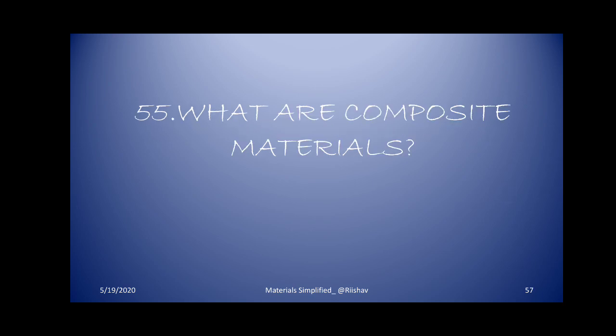Okay, what are composite materials? Well, yeah, composites are a combination of 2 or more materials. Okay, like one of them is matrix, another one is reinforcement. See, generally each of the materials we are using must exist at more than 5%. Okay, there are 2 different phases. One is matrix, which is the continuous phase, and another one is the reinforcing phase, which can be continuous or discontinuous both. So basically composites, why do we go for composites? Because I want better properties. Okay, so that's why we are going for a combination of two or more materials.